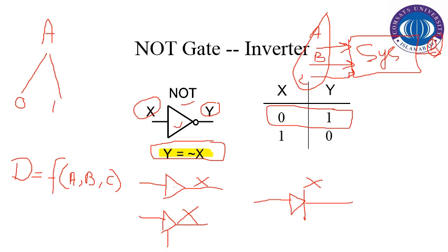So we have got an output Y that is a function of X and that is equal to not X. So NOT can be symbolically represented in an equation by this symbol. We will learn that NOT can also be represented with, for example, a bar on a Boolean literal, or we can say that we've got the X literal and X prime, which represents the NOT operation.